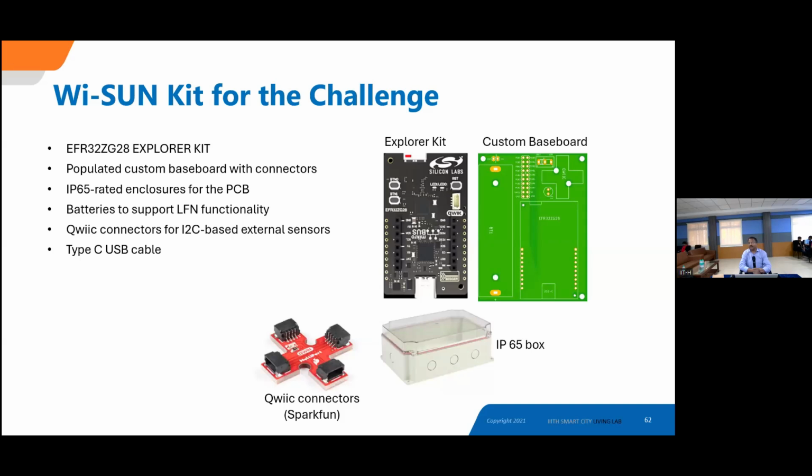it has a SparkFun multi-port I2C connector placed on the board, so that one of the four will be connected to the Explorer kit, and the remaining three are given to you for interfacing various sensors externally, which are supposed to be on the I2C bus.